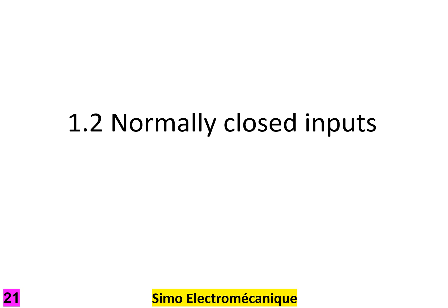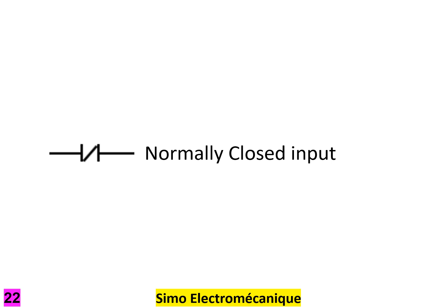1.2 Normally closed inputs. Here we introduce a new ladder logic symbol. This is a normally closed input. It is analogous to a push-to-break switch. In other words, it will activate with a logical 0 or the absence of current on its input. If a logical 1 or current is applied to its input, it will switch off.